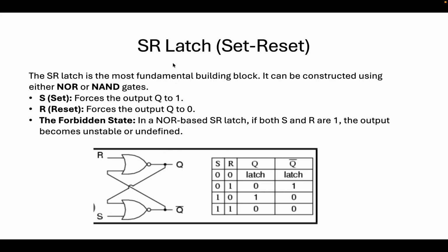SR latch. The SR latch is the most fundamental building block. It can be constructed using either NOR or NAND gates. That is, first one is set, which forces the output Q to 1. Reset forces the output Q to 0. Let us check how it works.